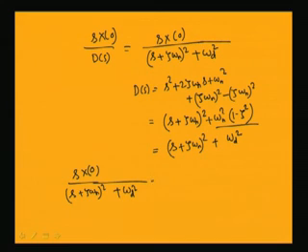So, I have to find the inverse Laplace. As this is s plus zeta omega n, it will contain a term e to the power minus zeta omega n t, and as there is an s in the numerator, you can think that there is a cos term.